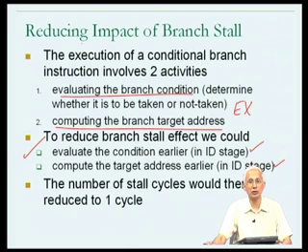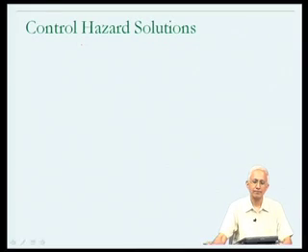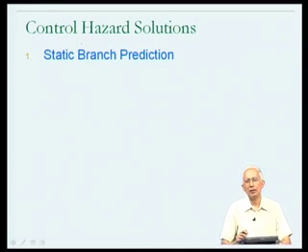We still have 1 stall cycle, and ideally we would want to have a pipeline in which the control hazard is fully handled, in other words where there is potentially no stall cycles. So, we need some more ideas to understand how such pipelines might be designed. Now, I am going to talk about a few ideas which are sometimes used in processors for handling control hazards, essentially to remove that 1 stall cycle which we were left with at the end of the previous slide.